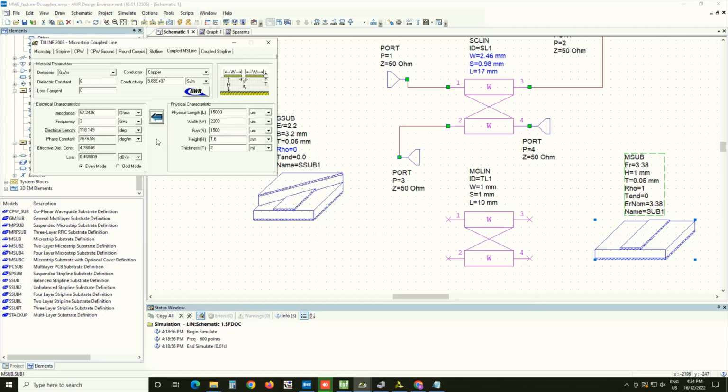It's close enough. You can then tweak it. Anyway, remember that you can get any even and odd mode impedance, right? That formula tells you that if you choose a coupling constant and the characteristic impedance, that gives you an even and odd mode impedance. But if you choose any two even and odd mode impedances, that will give you some corresponding coupling and Z0 as well. So it will not be matched for 50 ohms, but we can tweak that a little bit as we go closer to a better response. Okay, so let's start with this.